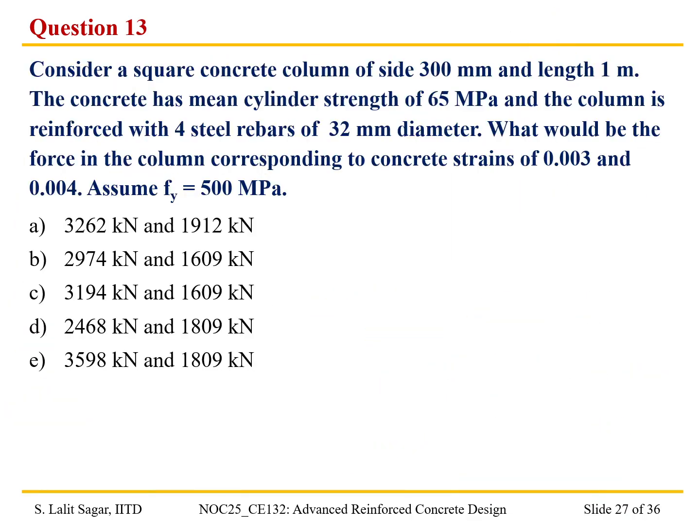Okay, so for the same reinforced concrete column, we need to determine the forces corresponding to the strain in concrete of 0.003 and 0.004.